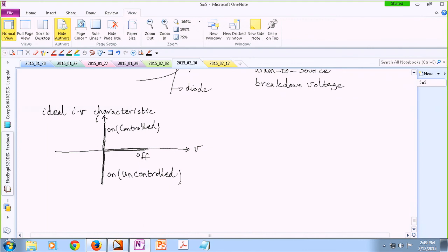Or you can actually turn the gate on, and the competition happens, or you can basically have a little bit of a control over it. So it's up to you which one you want to use. Now this region is not necessarily very popular. In a lot of applications, you tend to use your MOSFETs the same way that you are using your IGBT, which is a first quadrant switch. But technically, you can use your MOSFET as a device that can handle both positive and negative currents. And we're going to talk a little bit about this when we talk about synchronous rectification.